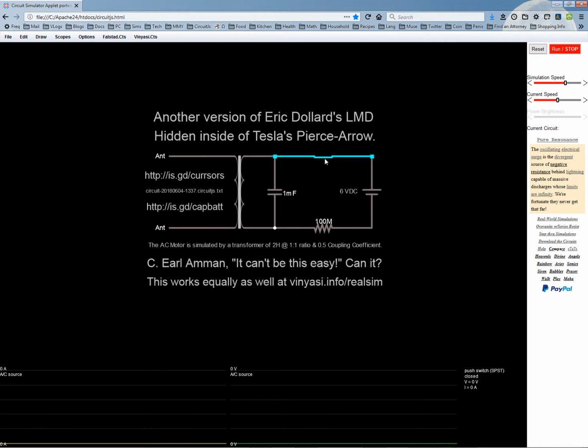And if you were to hold the switch down for any length of time, you'd see the current going around, and once in a while it would jimmy backwards for a slight moment and then go back forwards again. And you'd be draining the battery like crazy. It would explode long before, because in the simulator it goes up to kiloamps and whatnot, so you don't want to do that. So I put a resistor here to prevent that, and a snap switch. And I'm giving you instructions. Just a snap is all you need to get this thing going. The real magic is to raise and lower this capacitor. So let's stop talking. Oh, there is one other thing I have to tell you.